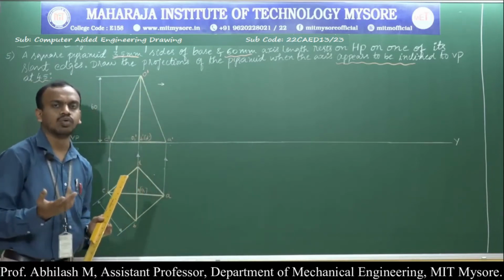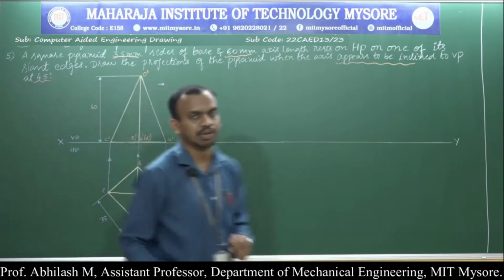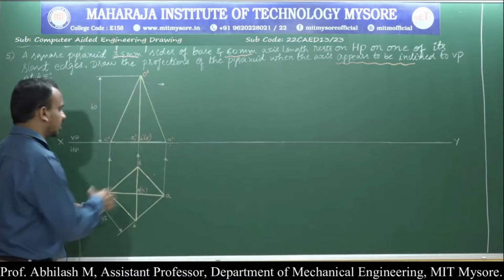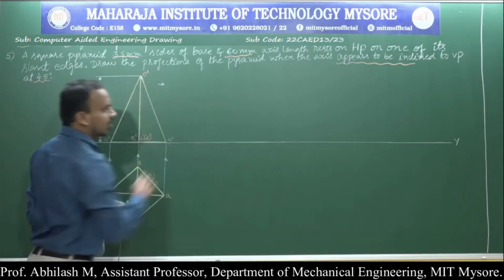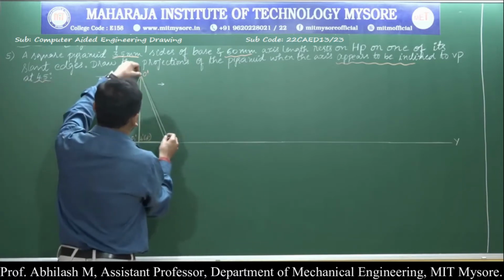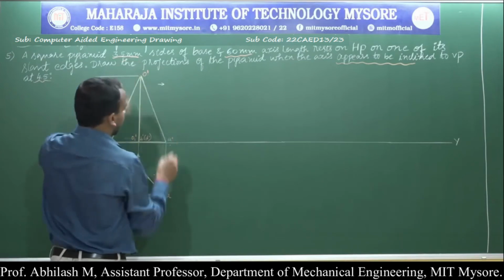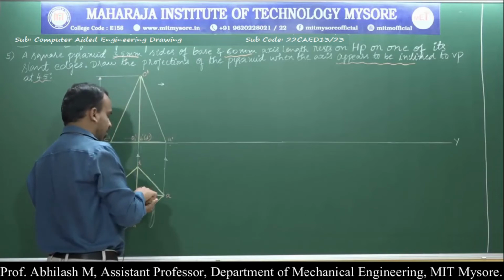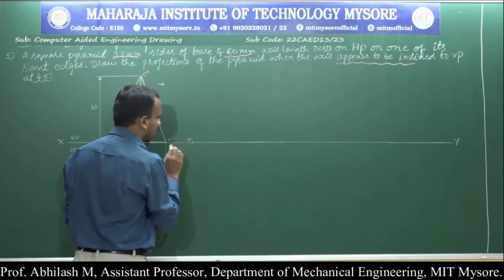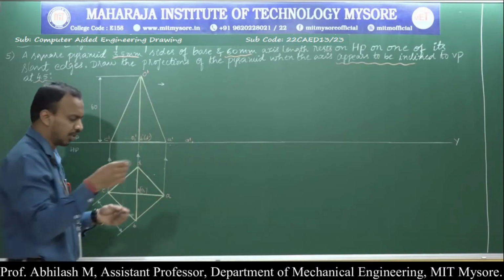How to do that? There are two ways to do that. One is with respect to the arc method. Take your compass and pencil and continue with that. You can just measure from the sides, or the other way is to transfer this completely onto the XY line. To begin with, measure from O dash to A dash. Identify a point first and call the point A dash. So I have identified the point A dash.